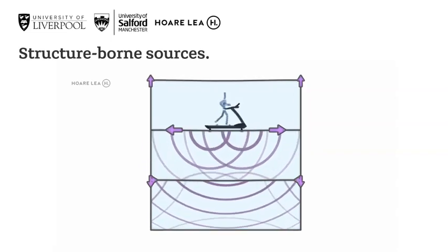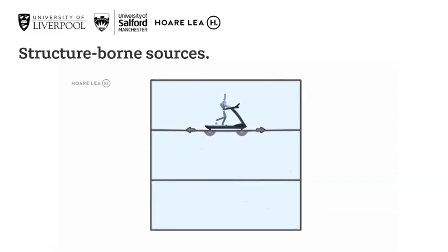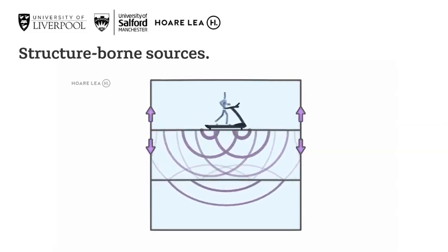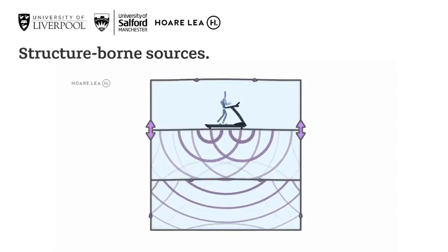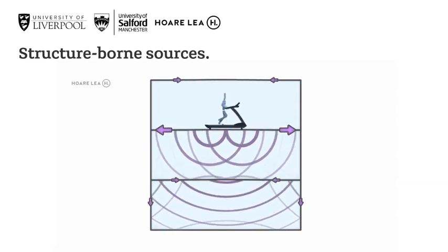At each structural interface, structural junction, the attenuation is usually much lower than that offered by the airborne component of floors, walls, etc. And as such, structure-borne noise can propagate freely through a building and affect not just its immediate neighbour, but neighbours beyond that as well.